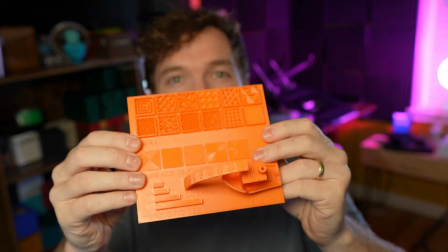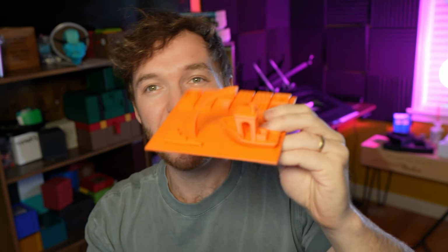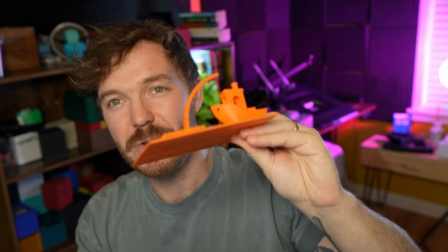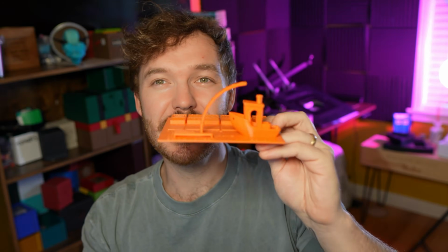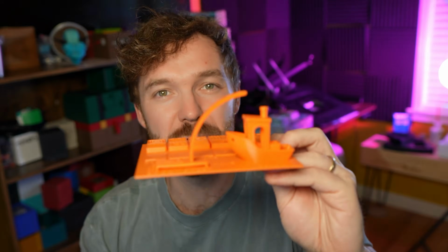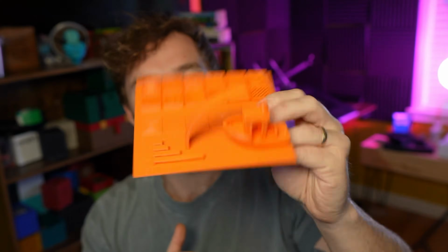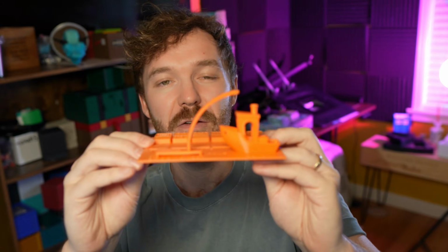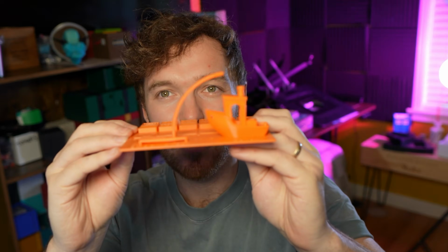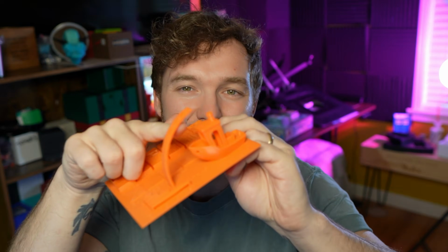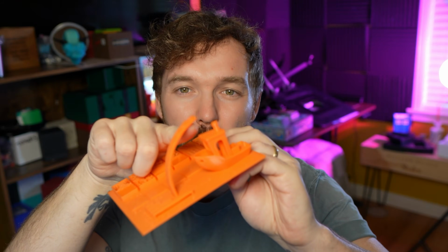This is a testing plate to test all the different things that you can do on your printer. I would recommend using one of these because then you can see the limits you can push your printer to as well. You can find these online. So yeah, they're fantastic. You can see this little overhang bar here. That'll show you how far it can go, and you can see where it starts to warp and not look so great. But as a rule of thumb, no more than 45 degrees and you're going to be golden.